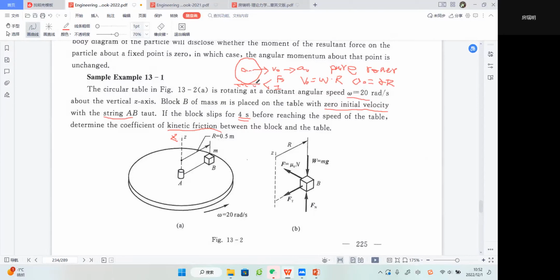So it means it will have a static friction, and this contact point will be the instantaneous center of velocity, 瞬心, right? If all these conditions are fulfilled, then omega must be along the CW direction. Maybe we give the same assumption for alpha, angular acceleration, right? Later we will do some examples, and maybe we will also use the conclusion.